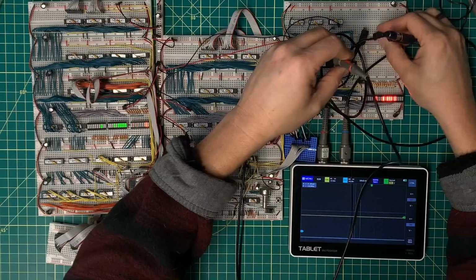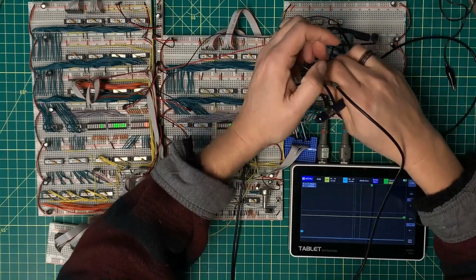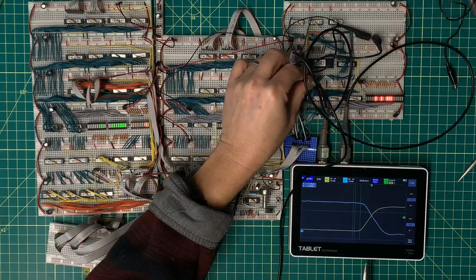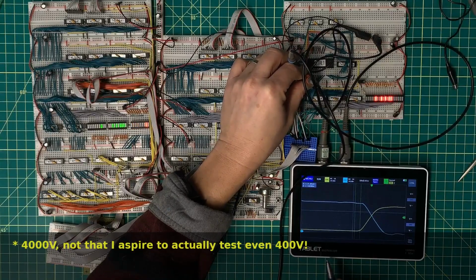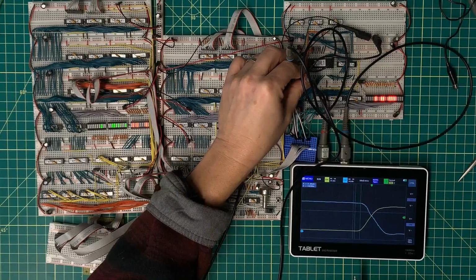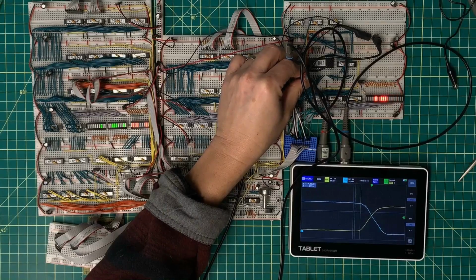My original thinking was that 10x was a measure of the probe sensitivity, and I've now come to realize that this oscilloscope has the ability to measure up to 400 volts, but it can only do so if it's in 10 times mode. Actually, it's up to 1,000 volts if you have probes that will do 100 times. But the typical 1x is up to 40 volts. Since I'm only measuring 5 volts nominally, it makes more sense to have these probes set to 1x, and then I get what appears to be a much cleaner trace.